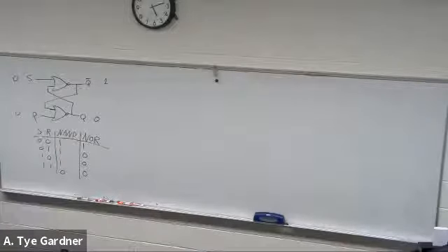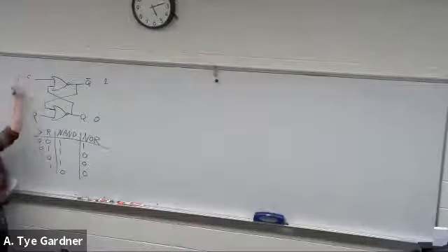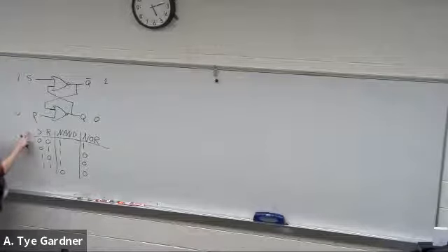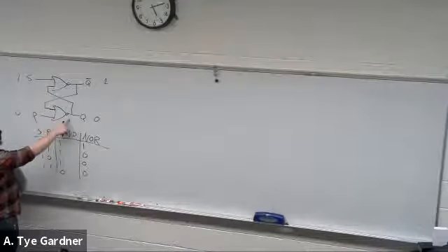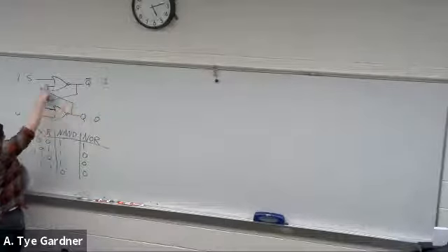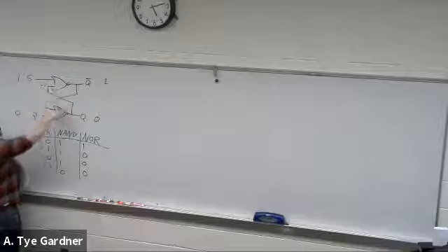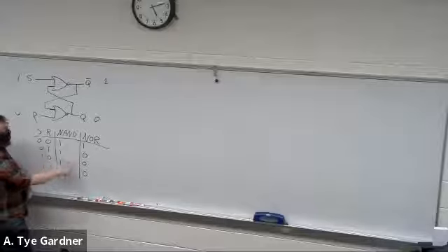And now, as long as I don't do anything to that circuit, as long as they hold electricity, those numbers are true. But what happens if we set? We raise it to 1. Now I go 1, 0 for set and reset. So in the case of Q, Q doesn't see set yet, right? Because it has to get the output of not Q. But the output of this gate, because I have a 1, 0, becomes 0.